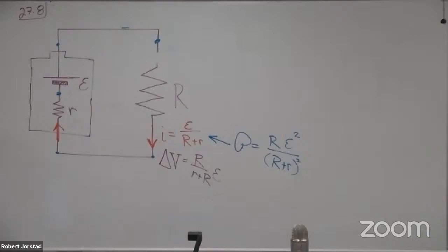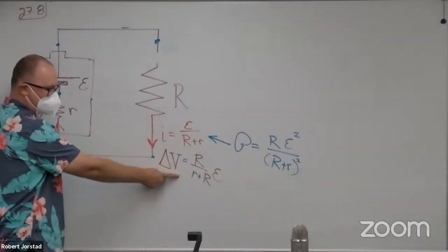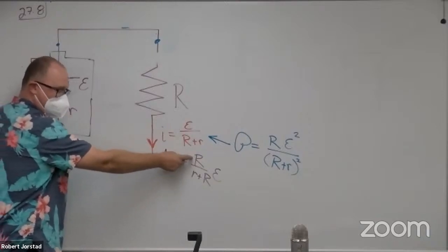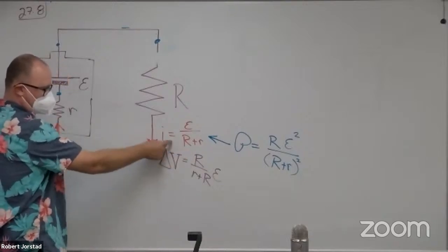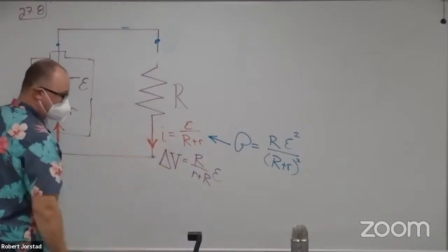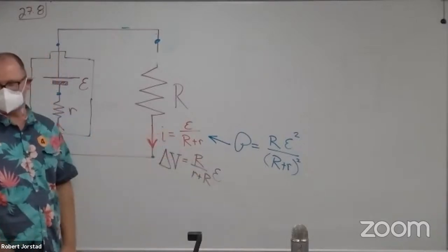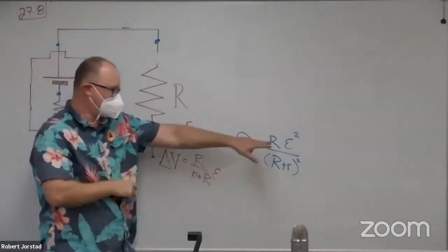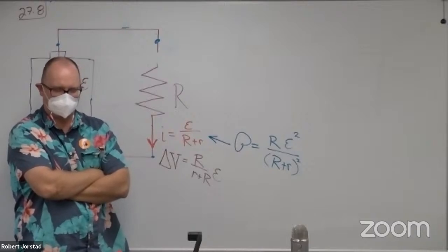Well, let's think. If you make this closer to 0, what happens to the voltage? Does it go up or down? It goes down. So if you decrease the resistance, the voltage drops to 0, the current goes up. If I increase this resistance, its voltage should go up, but its current's going to drop. Gosh, I just wish there's got to be some way to figure out what value of resistance gives me maximum power. What's that?